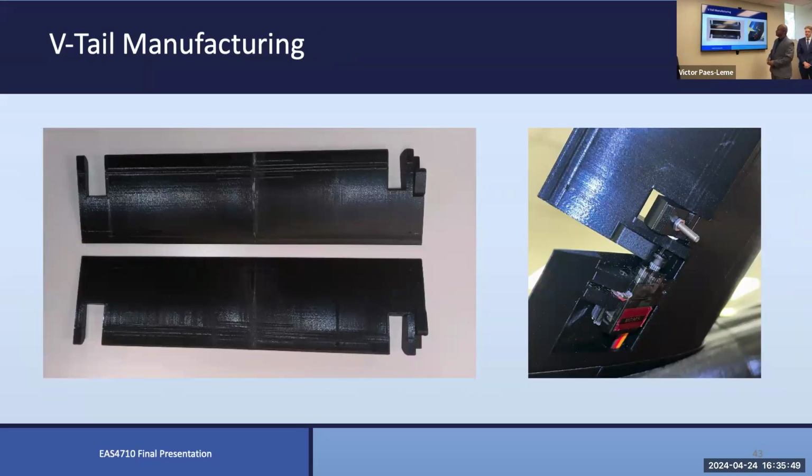And for the empennage, within the VTOL, our assembly or design process was to 3D print in PLA 2 sections and then attach them with a spar in the middle and then glue the middle section. And that was the design process for our stabilator. With the stabilator attached on the right, you can see the servo arm was directly attached into the stabilator, and it was connected via a carbon fiber hinge. And that allowed freedom of movement along the axis.